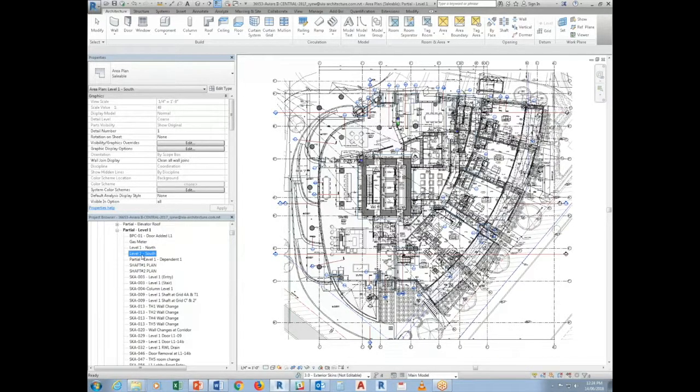I still don't understand, like, this could be call-outs too, no? Yes. The problem with callouts is that once you put a callout, it sticks to this plan. And if let's say you made a mistake and you want to move that callout to some other plans, you can't do it. It's fixed there, and you cannot move it somewhere else. That's the disadvantage of using callout, because callout just sticks there, and then that's it. It's not going to go anywhere.